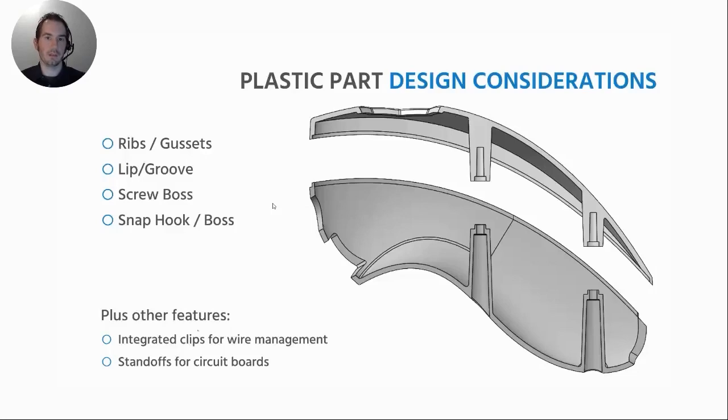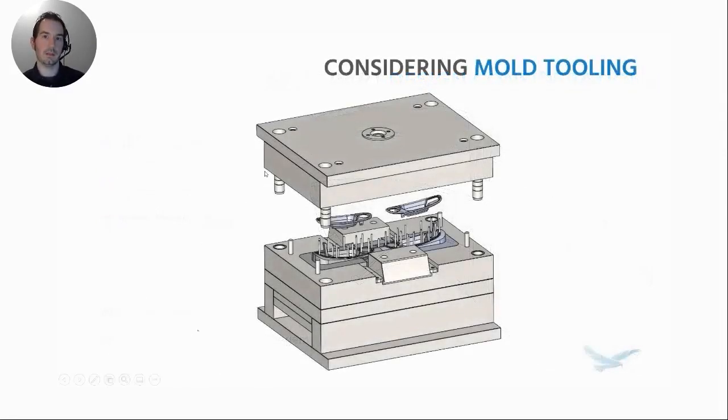So, integrated wire management clips for electronics. A lot of our customers deal with electronics, so integrated standoffs for things. Just reducing the part count that you might need in these plastic parts. And then, even if you're on the part design side strictly, it's always worth considering what the mold is going to look like. These are actually some screenshots from our mold tooling class.